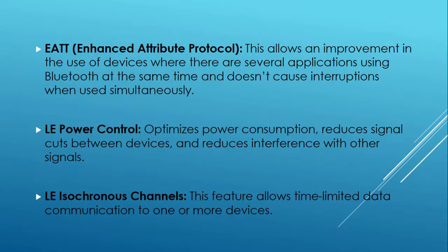EATT, this allows an improvement in the use of devices where there are several applications using Bluetooth at the same time and doesn't cause interruption when used simultaneously. LE Power Control optimizes power consumption, reduces signal cuts between devices, and reduces interference with other signals. LE Isochronous channels. This feature allows time-limited data communication to one or more devices.